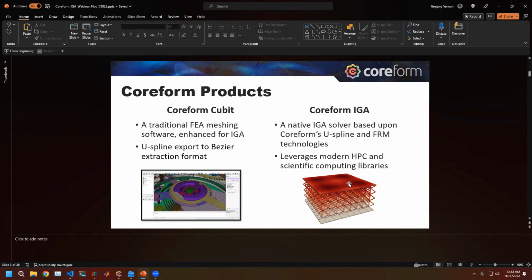Just to give some perspective, these models had approximately 200,000 to 600,000 degrees of freedom based on how complex the models were and how organic they were. In the scripting sense, the full prep to solution time would vary anywhere from about 15 minutes to about an hour with those caveats in place: single core, direct solvers, and in the hundreds of thousands of degrees of freedom area.